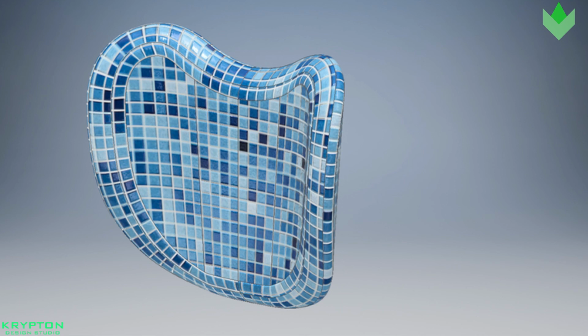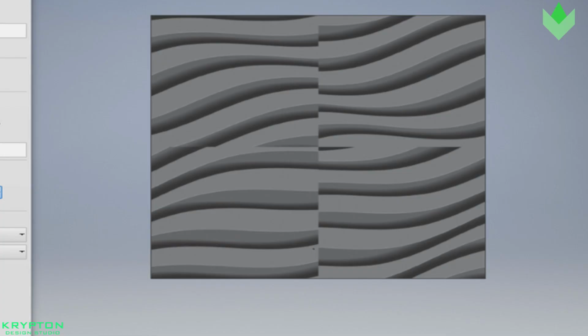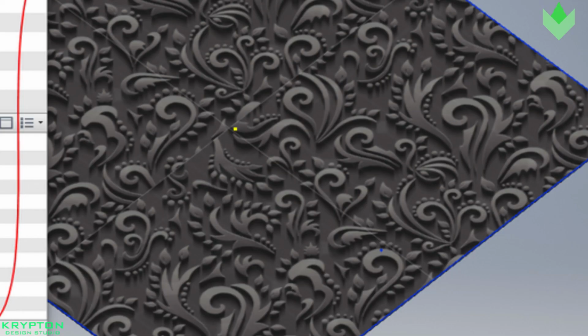Different textures have different impacts on the molded parts. The rule of thumb when designing for texture is to have 1.5 degrees of draft for each micron of the texture finish depth.